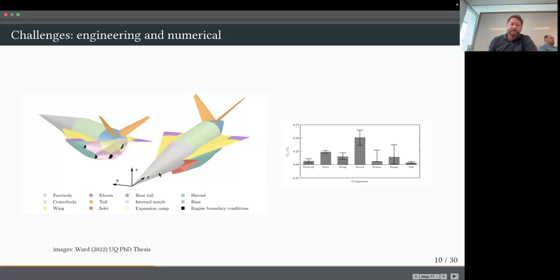But the challenge, and what keeps hypersonics exciting, is how tightly coupled all the aerodynamics is in one of these vehicles. If we look over to the right at the lift component, we see those inlets, the things that I'm specifically worried about for their compression, are actually contributing a rather large amount of lift to the vehicle.